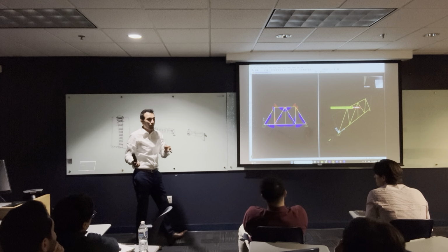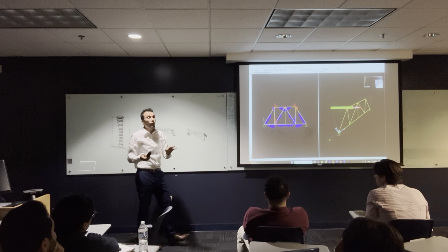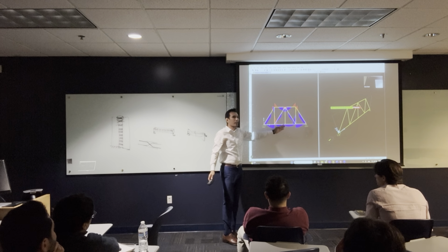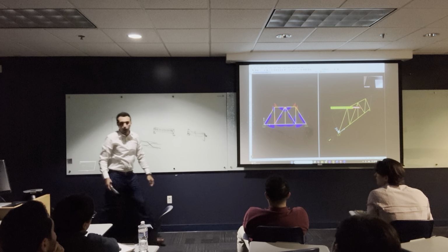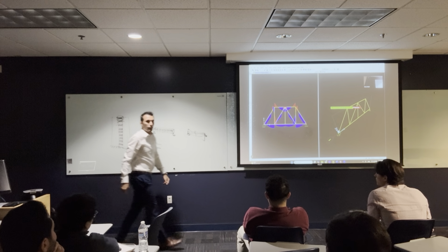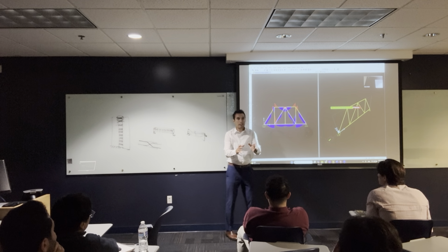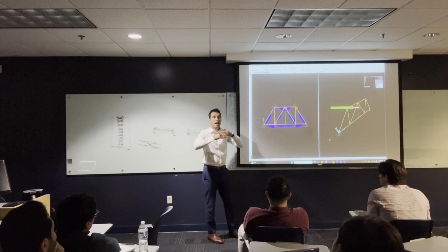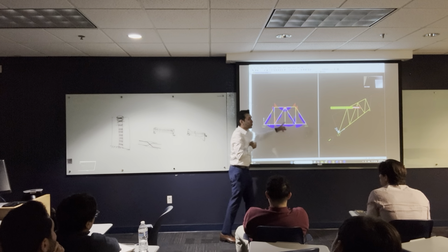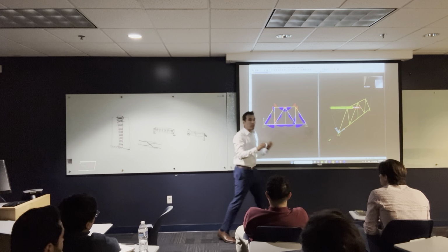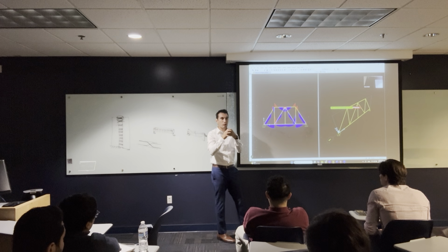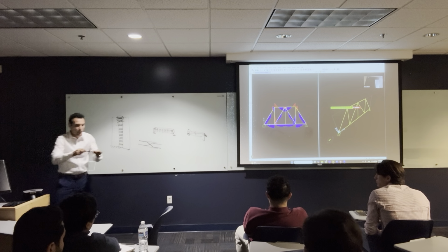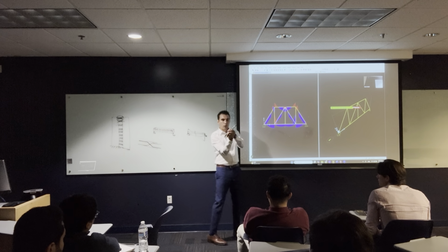Is that right? Like we have a truss that has a bending moment? That's not right. However, when we draw the truss, we draw it in a way that can develop a bending moment. Do you guys know how that happened? Probably the whole beam. Okay, that's one thing. For the releases. The thing is, when you drew this, how is the truss gonna know by itself if it's a frame and this point should have a bending moment? In truss, every one of these points is like an intermediate hinge, has a moment equal to 0.